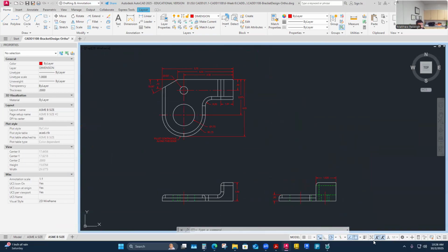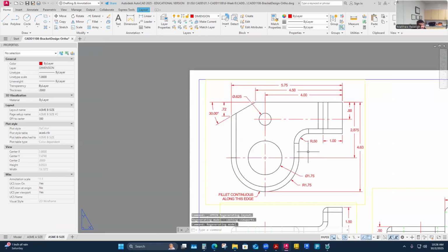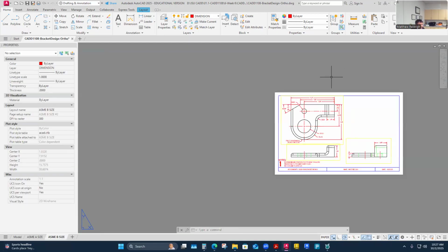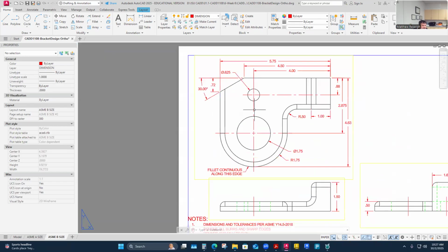So now that is the most critical before I even do line type scale. That's still the last thing I have to do, is fix my line type scale. But I'm happy. This is super critical: do not change the precision that was given to you, right? Do not do that because you'll probably affect the part's functionality every time. So hold the precision that you were supplied with at a minimum. And then I just need to fix line type scales.